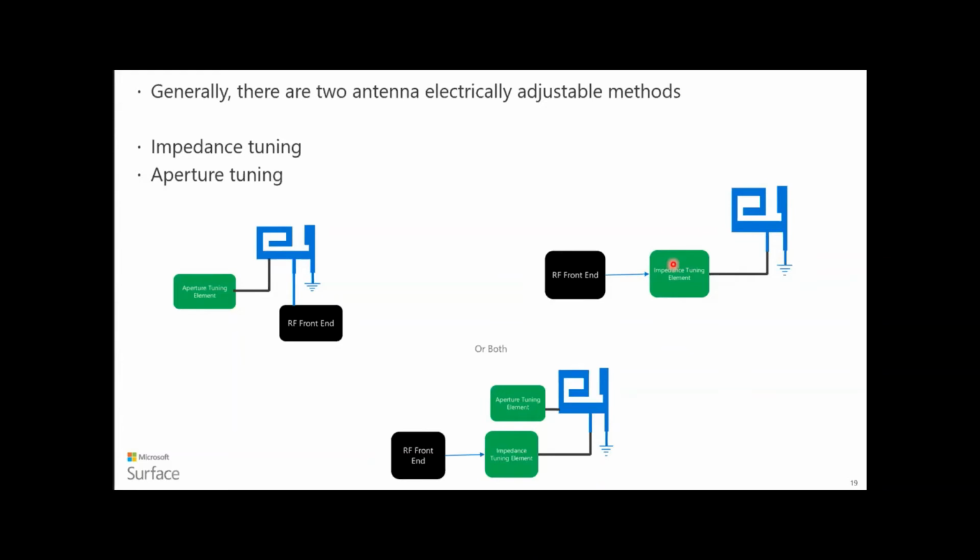We can try and impedance match the antenna across the frequency band of interest with a tunable capacitor, which is one kind of element that we use with switches in combination to effectively have a pi match that is reconfigurable. So we can have, say, a 3-element pi match that we can reconfigure with different values to tune over different frequencies. That's one way of doing it.